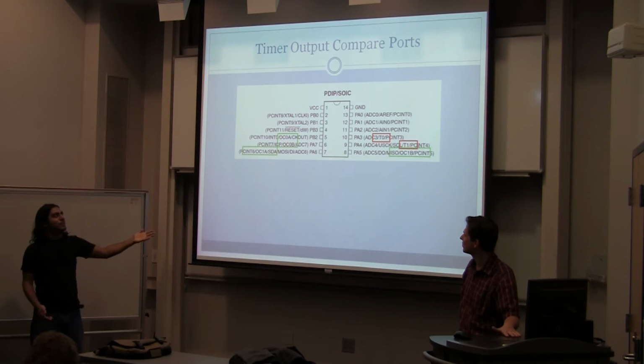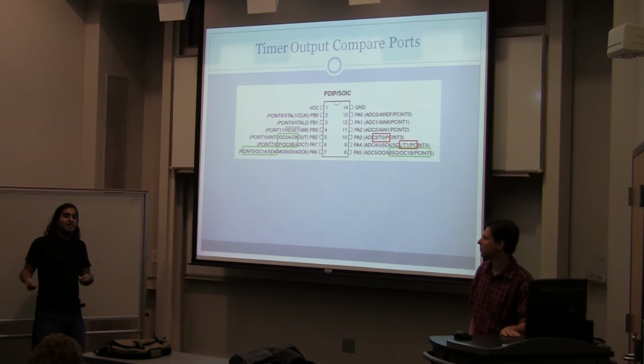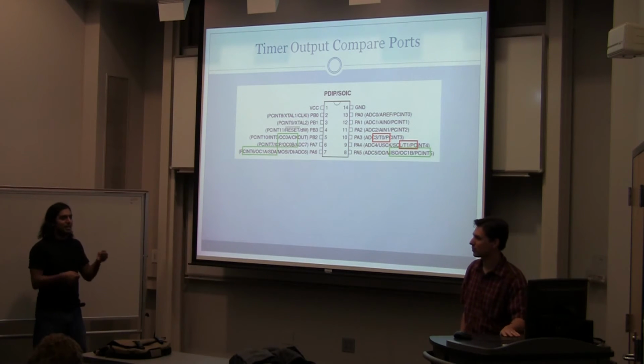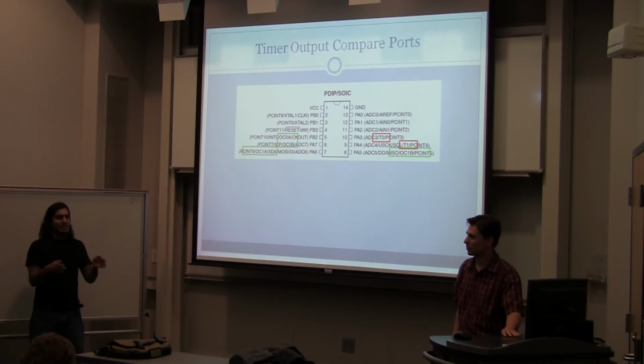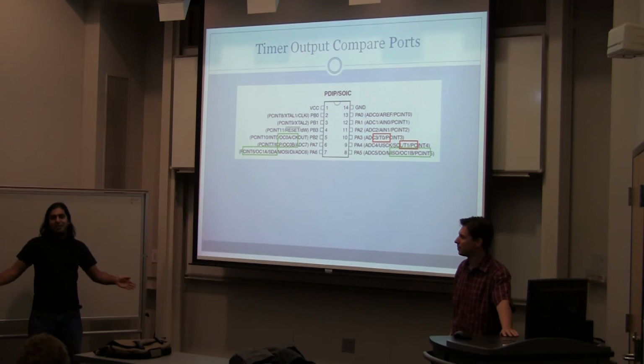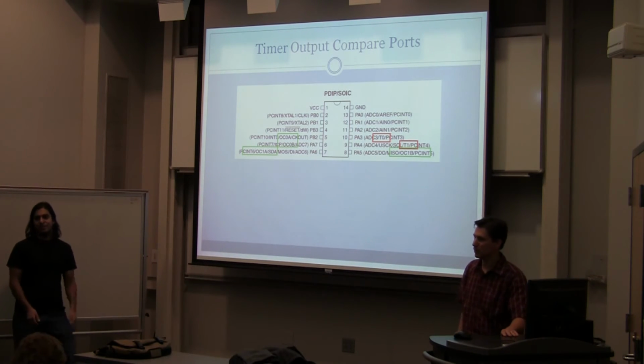And in most of these microcontrollers, each of these pins is carrying 5 or 6 different functions. So when you're designing your gadget, you have to keep in mind that the actual physical pins on your device might be a lot fewer than the functions that are available on your device. You might have 8 ADC channels, but 3 of those channels are also being used by something else that you need for some other function.